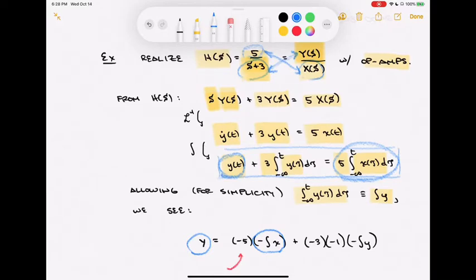I could have put that with the integrator. I choose to do it outside of the integrator in this particular case. So I'm going to take a gain of minus 5 onto that, and I'm going to make that as part of my summing node. Now, because each of those two terms, each of those two pieces, are constrained to have negative gains, when I do it together, I'm going to get the desired plus 5 that I had in my original equation.